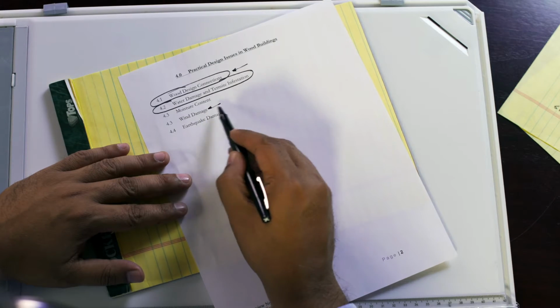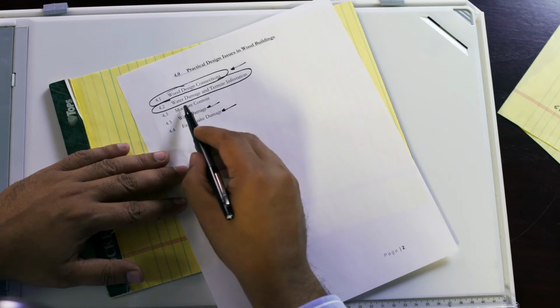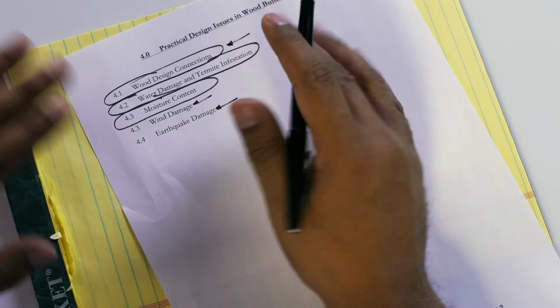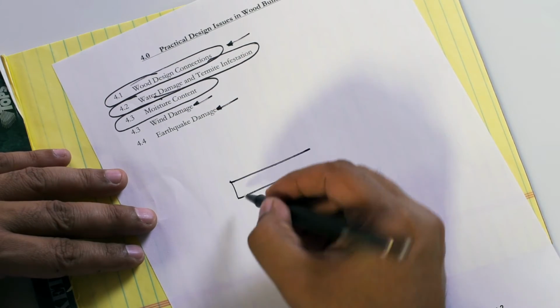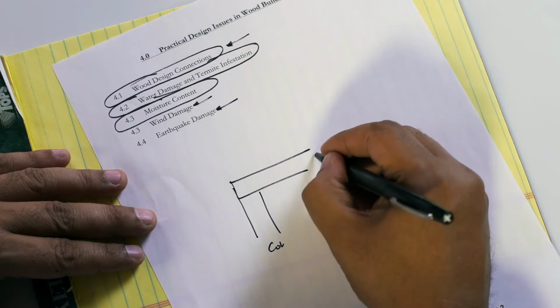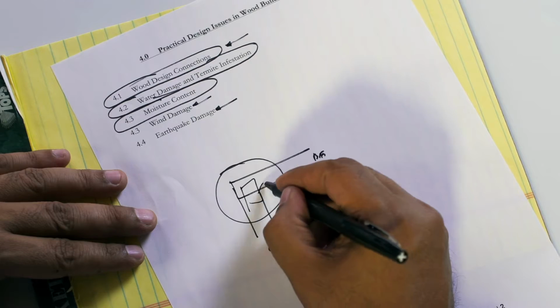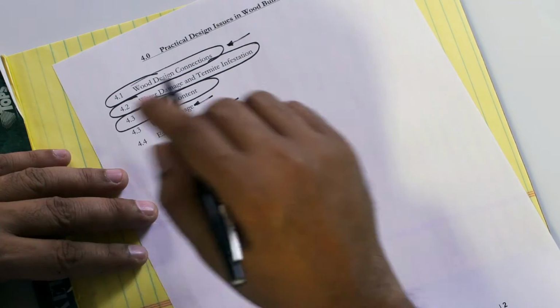And I want to show you some examples. Of course, you see a lot of wind damage, you see a lot of earthquake damage when earthquakes occur, but by far, if I had to pinpoint of all the wood failures that I examine, the 3 big problems: connections, which is where my beam comes in to meet my column. This connection in here is a problem. It ends up with cracking, ends up with all kinds of issues. And the other one is wood damage with termites.